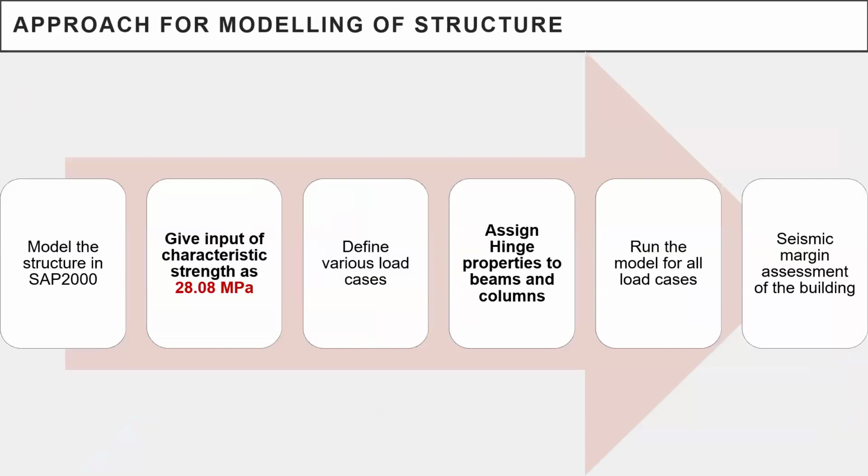So this is the approach for modeling of the structure and analysis. We model the geometry, define the material properties, define the boundary conditions, and define various loads. Then we assign the hinge properties, which are an input parameter to the nonlinear seismic pushover analysis, to both beams and columns, and then we run it to calculate the seismic margin of the building.